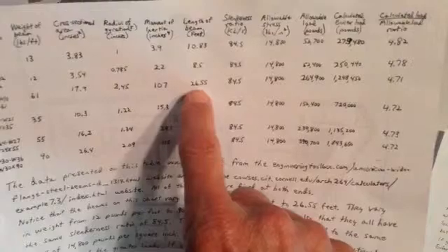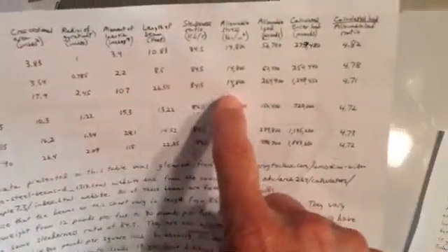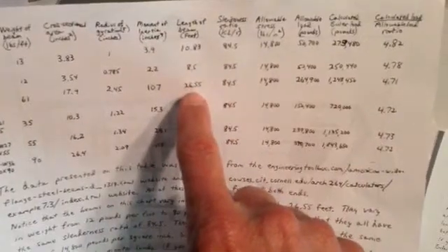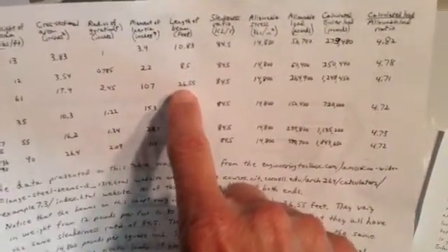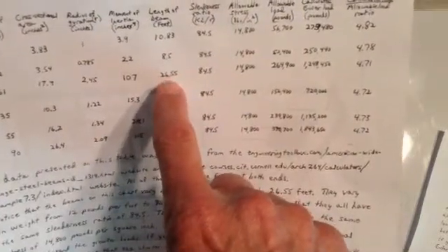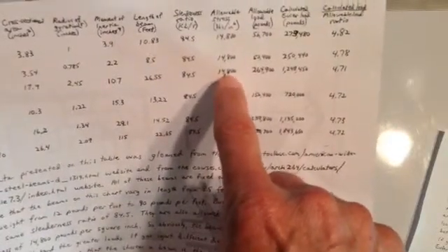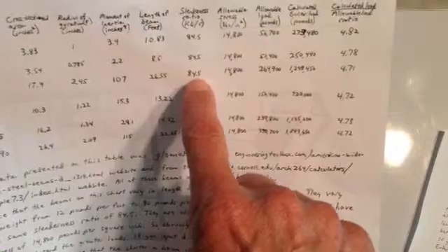This 26.5 foot beam gave us that slenderness ratio, but instead of 26.5 feet, we're going to look at a bunch of different lengths between 1 and 60 feet. So our allowable stress won't be 14,800 anymore, and our slenderness ratio won't be 84.5 anymore.